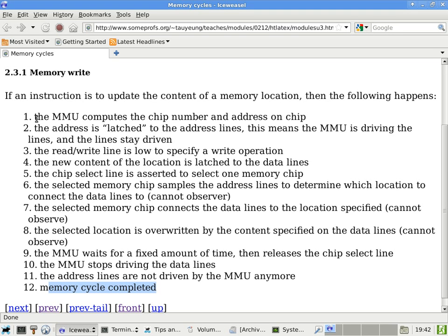Now, since we are on this discussion here, do you think that algorithms can make a difference in terms of the actual speed of execution time? If you have an algorithm that has a lot of sequential reads in memory locations, then you can utilize DDR2 and DDR3 to their maximum capacity because you are always interested in following locations and following locations. So when you pre-read in burst mode, when you pre-read into the cache, guess what?